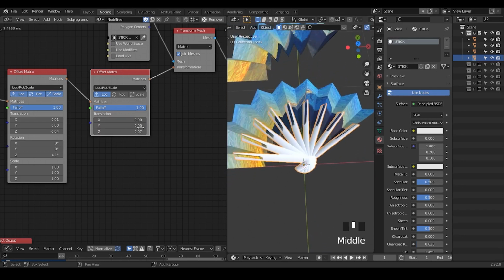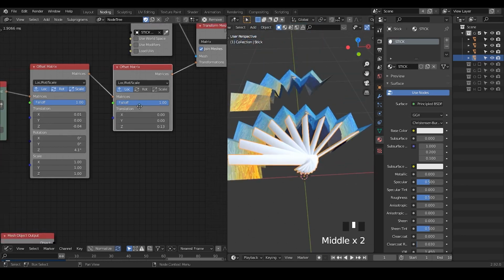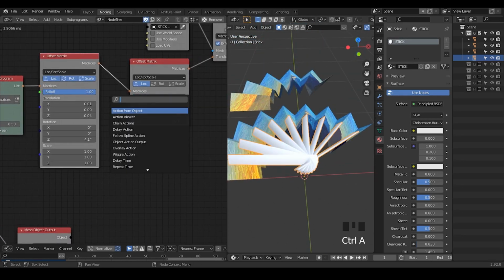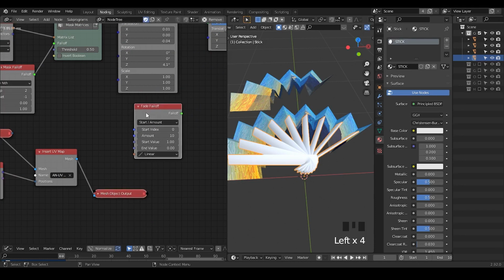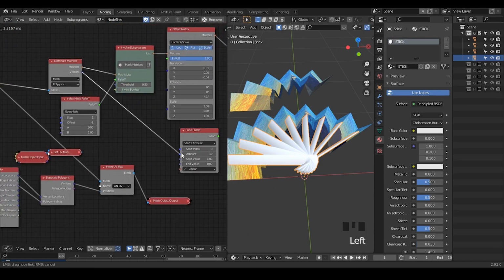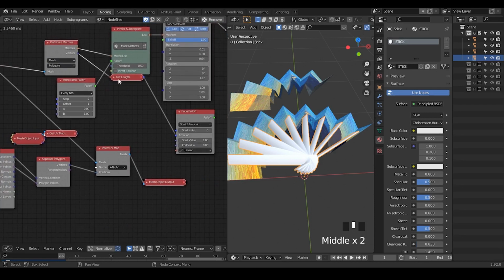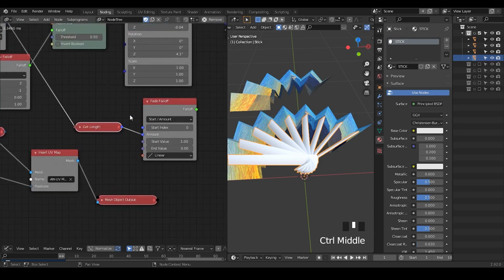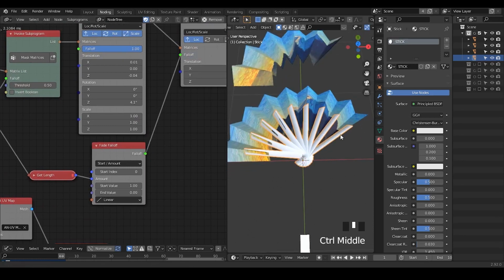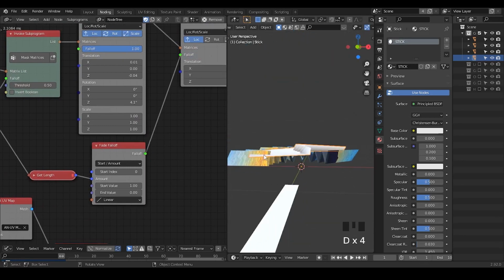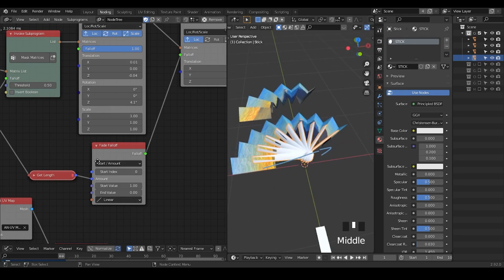Okay. So the way to do that is, basically, how should I say? There are really many different methods, but I'll just use the fade evolve. This is not necessarily the best method, but it is the most convenient method in my opinion. And I need an amount. I can get the amount from anywhere: matrices, vectors, whatever place. As long as the amount matches, it does not really matter where I get it from. Once I have this fade evolve, you can see there's a gradation from this to that object.